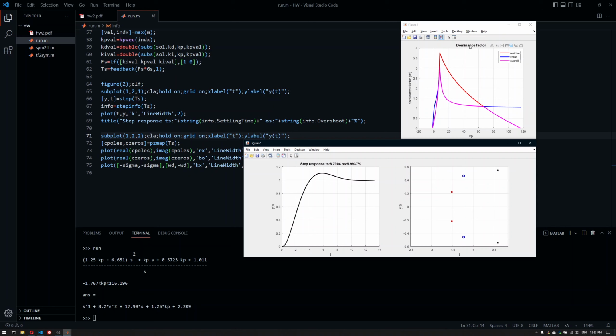Now, keep in mind that what we're trying to do is model a high order system like a second order system in order to be able to define the settling time and overshoot of that system. We don't have the necessary tools for high order systems to predict their settling time, overshoot, etc. That's what we are trying to do here.